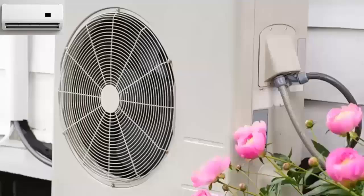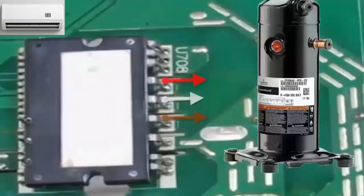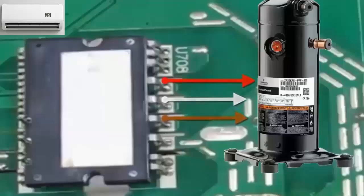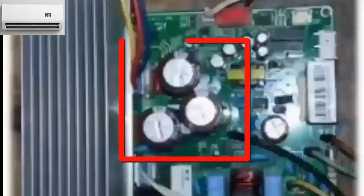F. If the problem is still not identified in an inverter system, suspect the IPM, intelligent power module. The IPM is part of the outdoor electronic board in inverter-type air conditioners, and it powers the compressor. Before performing any tests, disconnect the unit from the power supply. High-voltage capacitors may store dangerous energy even after the equipment is turned off.